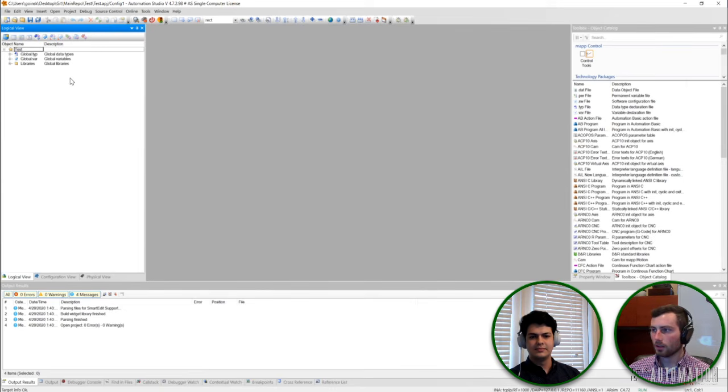Yes. All right, so I think that was a really good summary. Hopefully that was useful for those of you out there that are kind of new to this, or at least new to it in the context of Automation Studio. Again, what we talked about today was Git at a high level. What does the workflow look like? We talked about some of the best practices, so keep those in mind for sure. And then we looked at live how to make a change in Automation Studio, then commit that and push it, and then also how to check something out if we ever wanted to revert back.